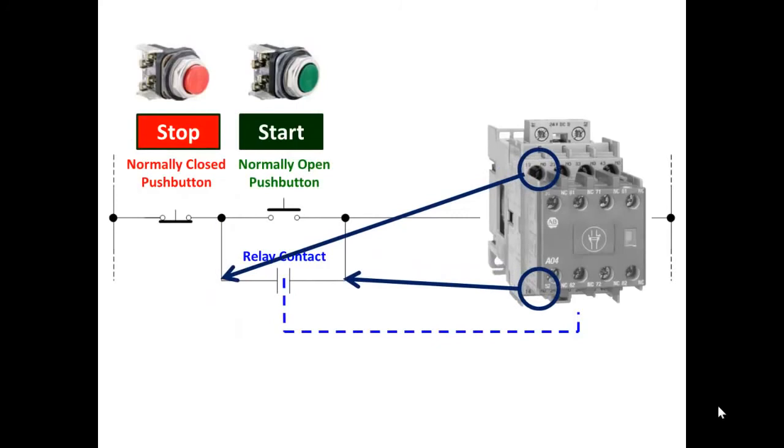Now, I'm very familiar with these relays, and I realize you might not be. However, I can tell by looking at the numbers on the screw terminals which two terminals you would wire up in parallel with the normally open push button for a normally open contact to bypass the normally open push button to seal in the coil. Now I have them marked there.